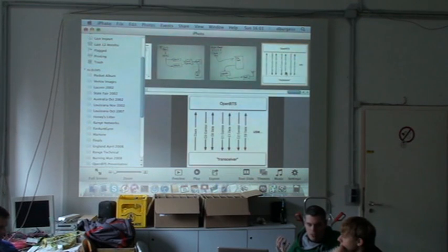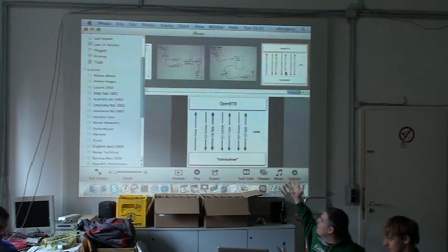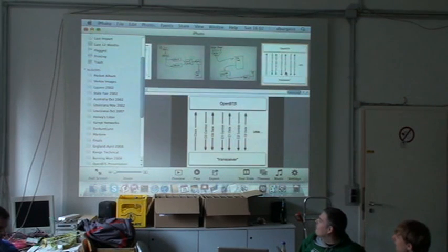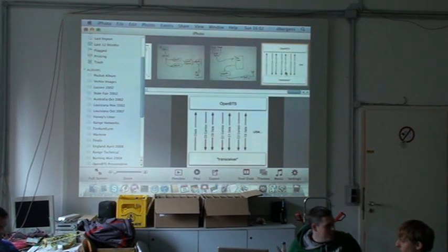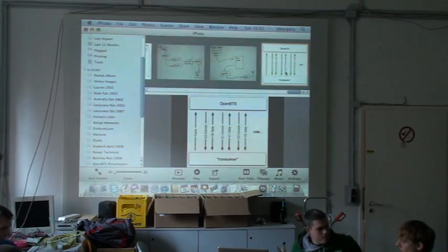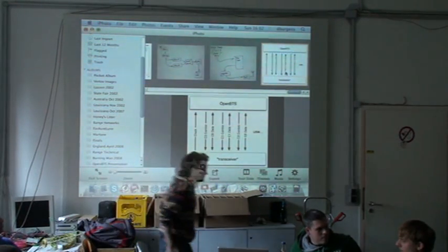No, I was just wondering, if you split it physically, the OpenBTS process and the transceiver hardware, and there's some kind of memory limitation, exactly what you need to store. Oh. Well, usually these things don't run more than about half a second ahead of real time. So you shouldn't need to store more than about a second's worth of data.